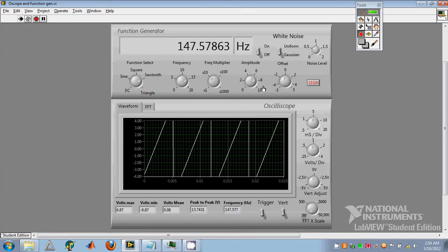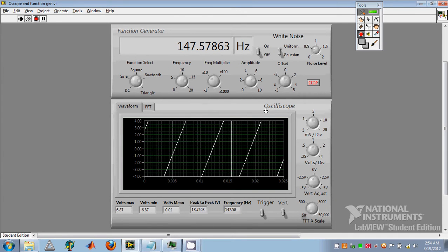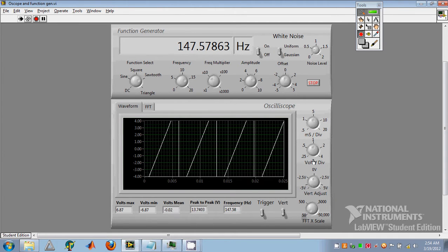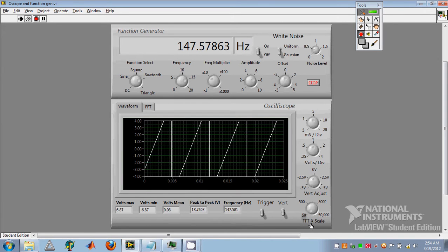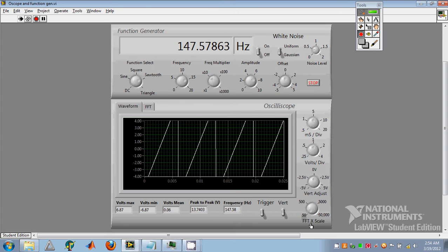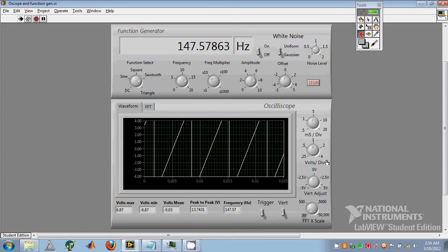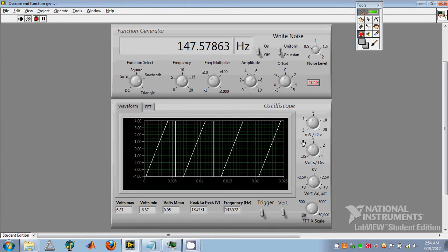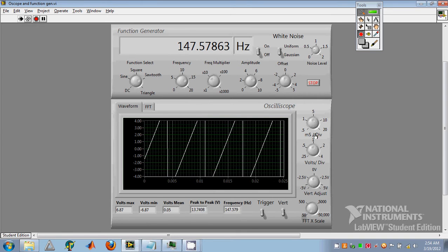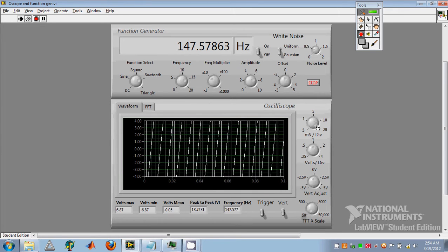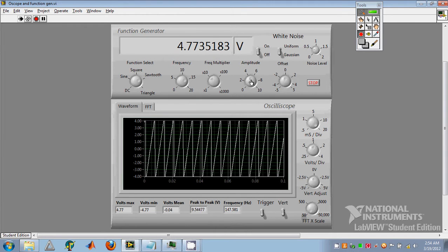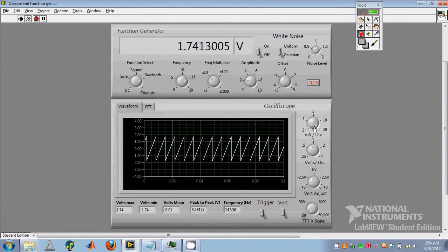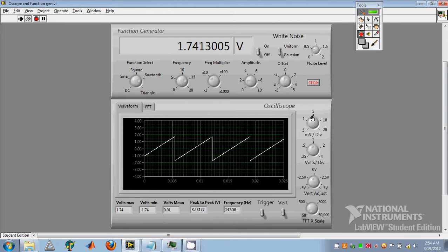Now let's take a look at the oscilloscope. I use three property nodes, one for the spectrum analyzer horizontal axes, and also for the volts per division and the timing. Each of these have 5 different resolutions as per the instructions. The maximum is 20 milliseconds per division, going down to half a millisecond per division.